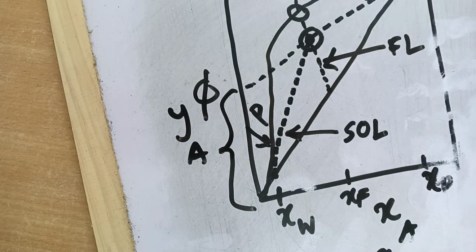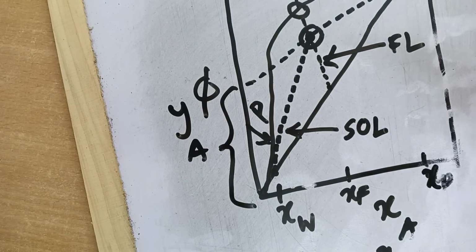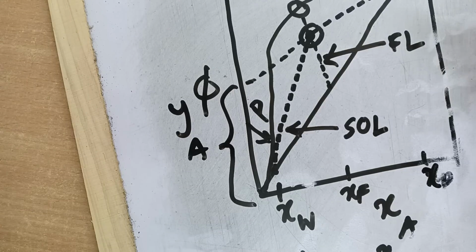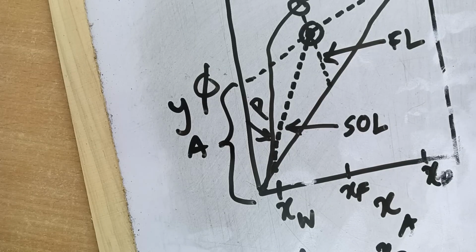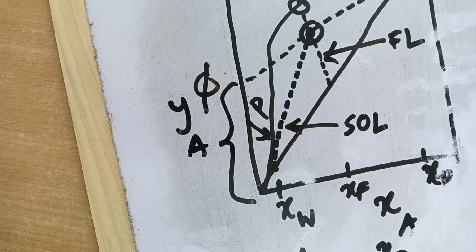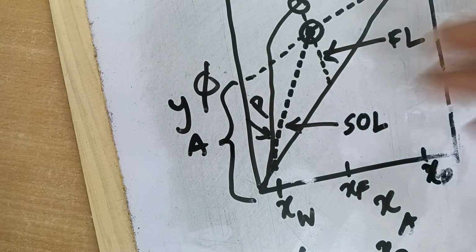So yes, in distillation column design, the pinch point normally locates somewhere close to the feed point, because all the time these operating lines and feed line merge with the equilibrium line in and around the vicinity of the feed plate, in normal practice. But there can be cases where the pinch point location can be in the enriching section or maybe in the stripping section like this.